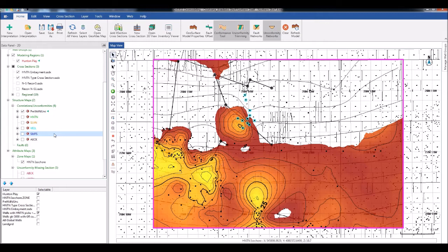Make a grid of intersecting cross sections to define the limits of the play by either importing existing X-section cross sections into the geomodel, or directly within geomodeling with buffered cross sections, or by creating cross sections from selected well-based wells from the map view. Pick the desired tops on all the cross sections. Use quick picks if necessary to improve picking performance.